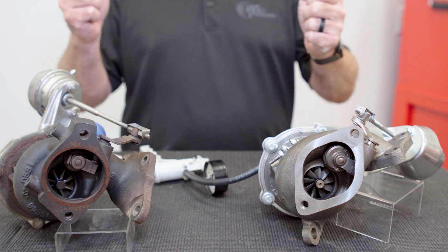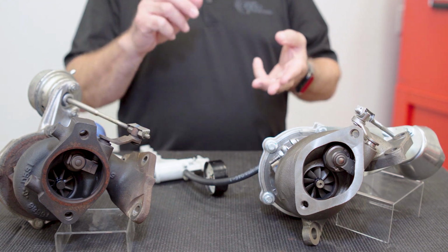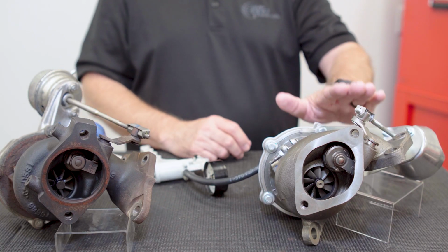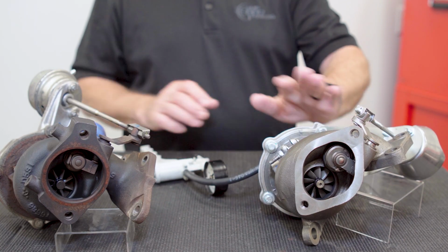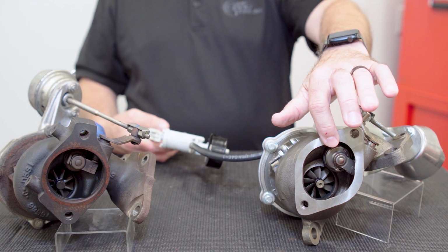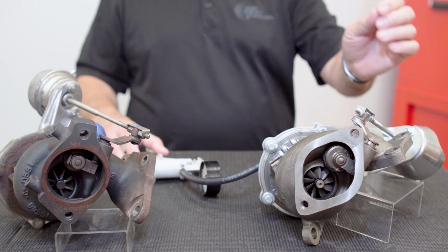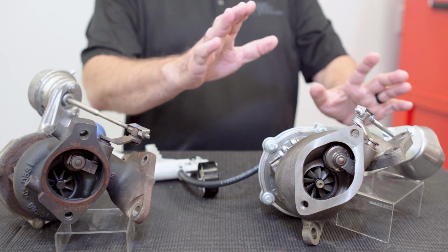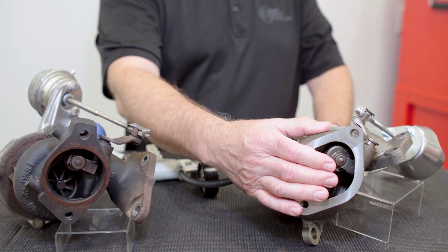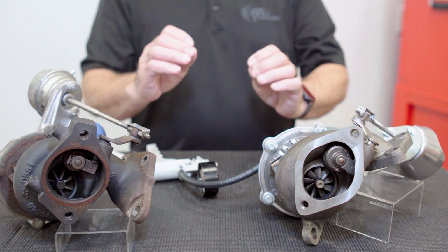With your scan tool PID selection, you can select map sensor, you can select boost pressure, and different pressures to see if they change. Now remember, you're supposed to have even a slight bit of boost at idle. If I actuate this wastegate actuator and that wastegate opens, you should see even a slight change in pressure. If you don't see that pressure change, that means that, okay, now I've got to go a little bit further, tear maybe the exhaust downpipe off of it if it's not too difficult to get to. But at this stage, let's pause for a minute.